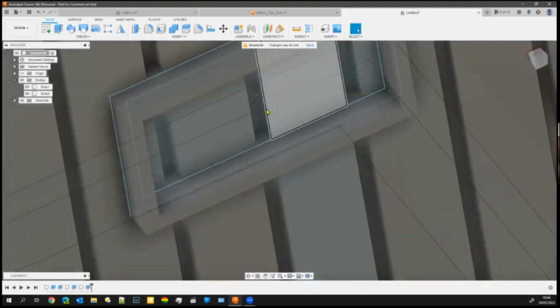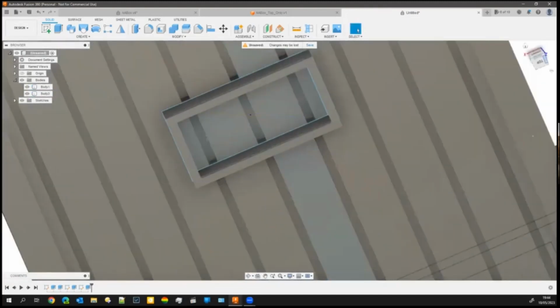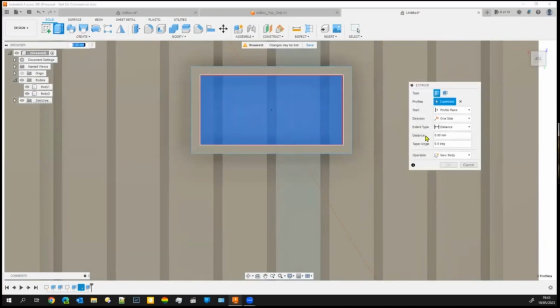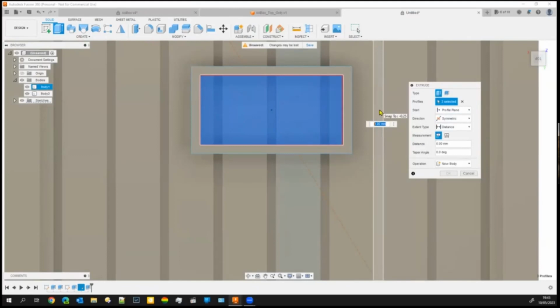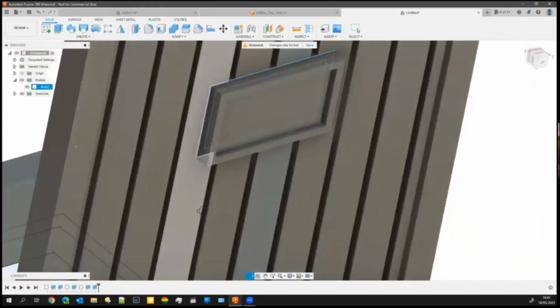Now our next move is to create one plane at the back, as it were, to put our number on. So again, we click on that one, hold the shift key down, click on all the bits, and we're going to extrude it. And again, we're going to go both ways, so we fill in these gaps behind it. So it's symmetrical again, but we don't want to come far, so 0.25, because if you remember, that was the depth of the grooves that we did. And don't forget to take that back to join. And you can see now we've got our box done.